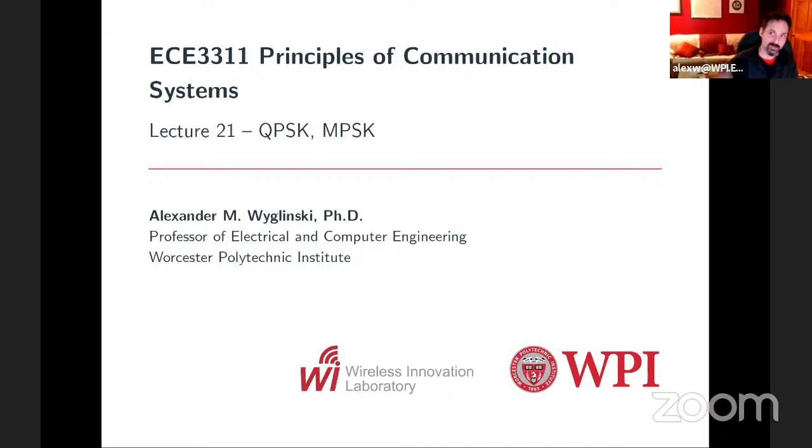In this case, it's a digital message signal, and we're taking B bits, which translates into one of M possible modulation waveforms that gets represented by a baseband signal every TS seconds, so every symbol period. And we convert that into an amplitude, phase, or frequency. As we'll see soon, we can actually take combinations of those.